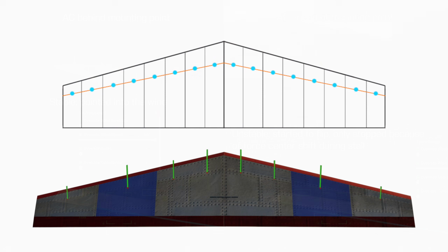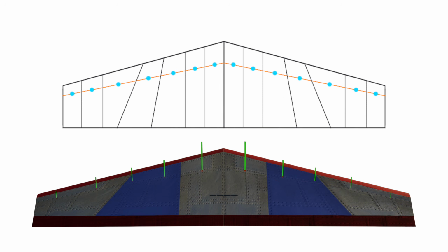I believe the cause of this involves Flyout's version of blade theory. In other flight simulators that use blade theory such as X-Plane, a wing is divided into multiple smaller segments, or blades, and the aerodynamics of each element are calculated individually. Each element also has its own aerodynamic center, rather than having one singular aerodynamic center defined for the whole wing. Flyout takes a similar approach, but differs in that the elements can be shaped such that their edges are not purely chordwise. I believe this causes their aerodynamic calculations to go awry, which causes the discrepancy shown earlier between two wings that should behave identically.